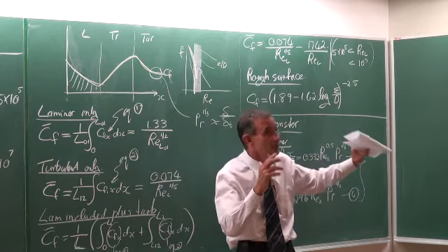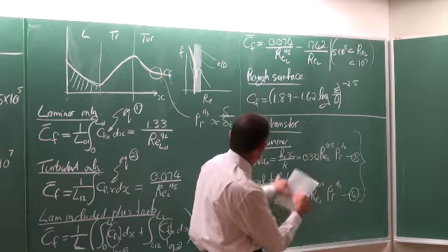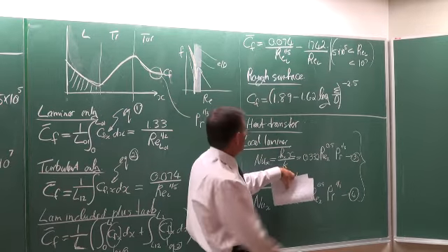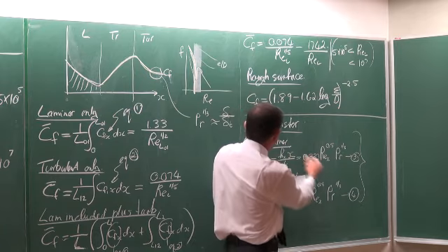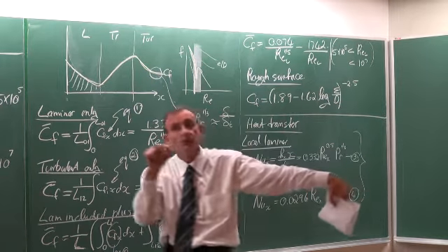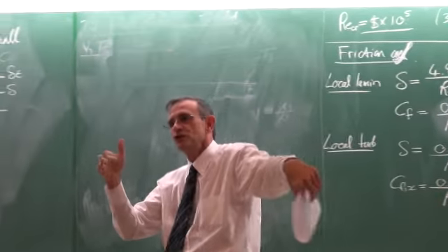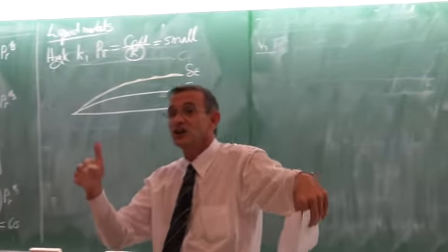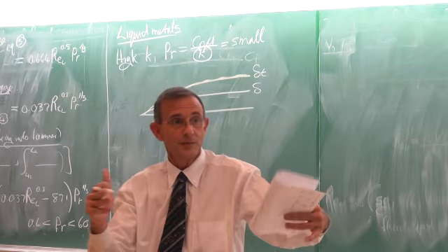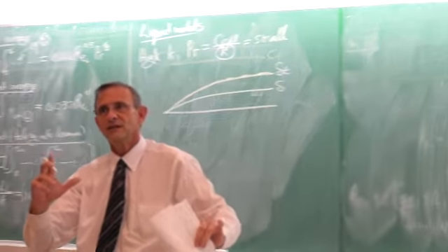But if you think about it carefully, remember that the thermal conductivity is coming in. Although you now calculate the Nusselt number, to get the heat transfer coefficient you have to multiply with the thermal conductivity. So something with a high thermal conductivity is going to give you a high heat transfer coefficient. So you cannot just use the Nusselt number. The Nusselt number doesn't tell you enough. Remember, in the Nusselt number is the thermal conductivity.